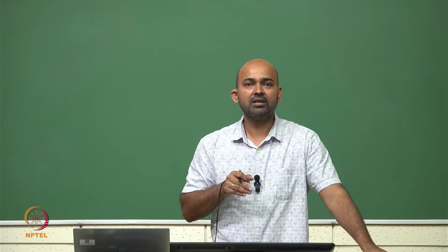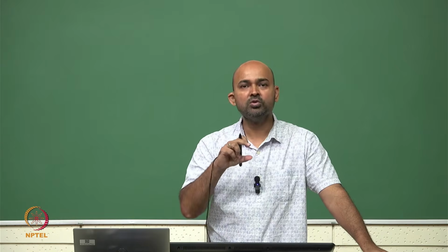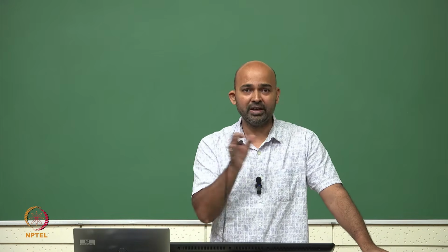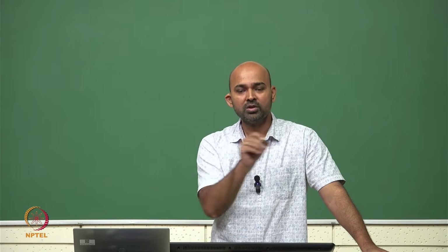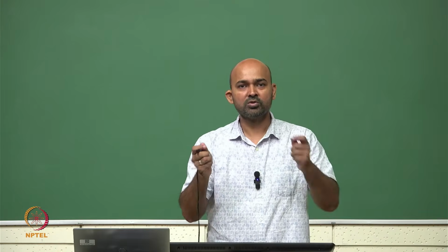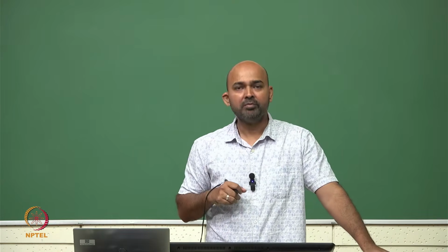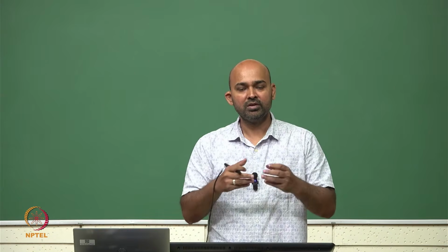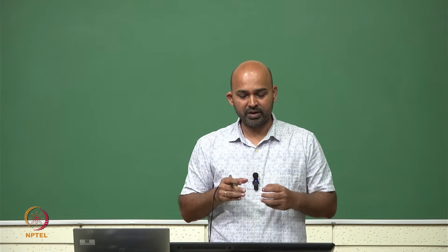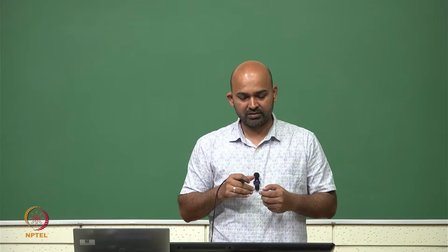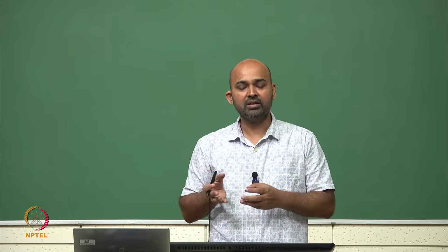So those two nodes where the inductor is connected, for example between node A and node B, will be connected by a simple wire, or those two nodes will be merged together. Then SPICE is going to solve those mesh analyses, performing KVL, KCL and all other techniques to arrive at the output.